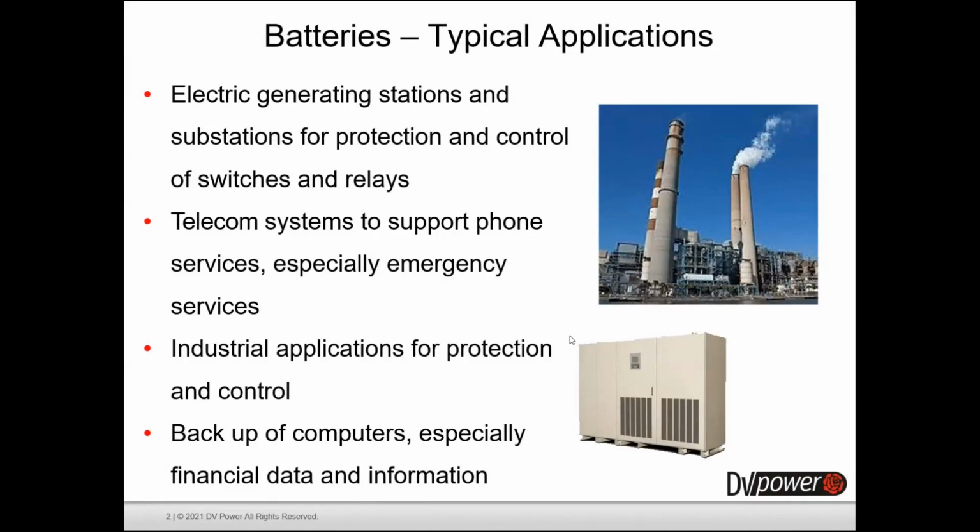Well, the diesel engines will start and provide enough electricity to supply everything. But the diesel engines cannot start immediately. You need them to start, you need them to synchronize, because it's always more than one, and that process can take up to 20 minutes. And what will happen in the time gap between the grid outage and when the generator starts to supply full electricity?